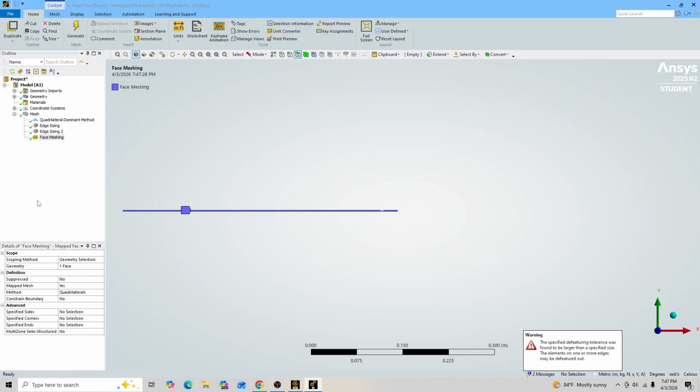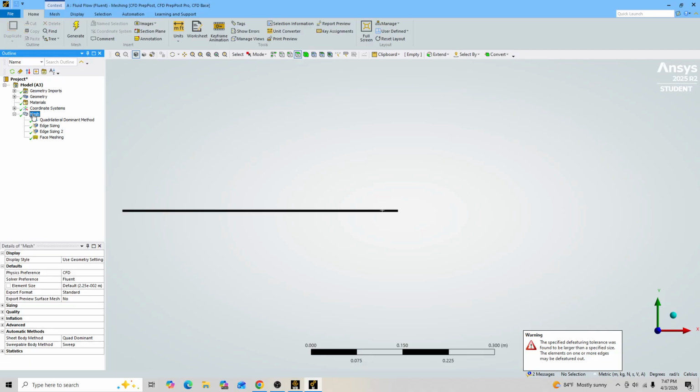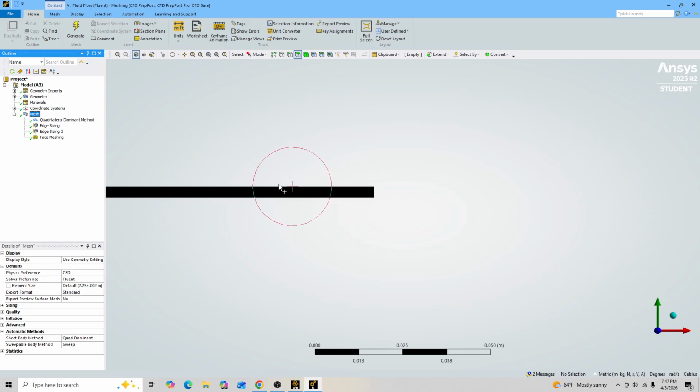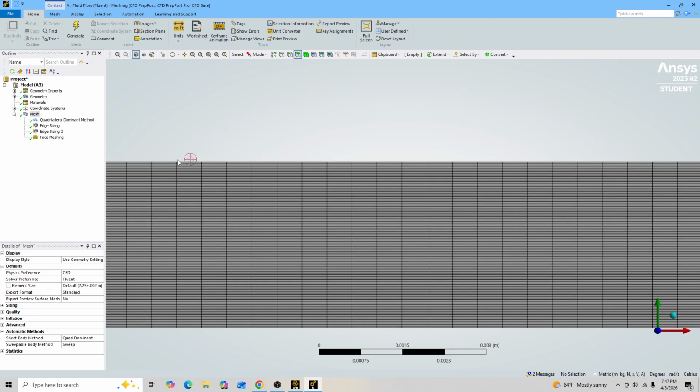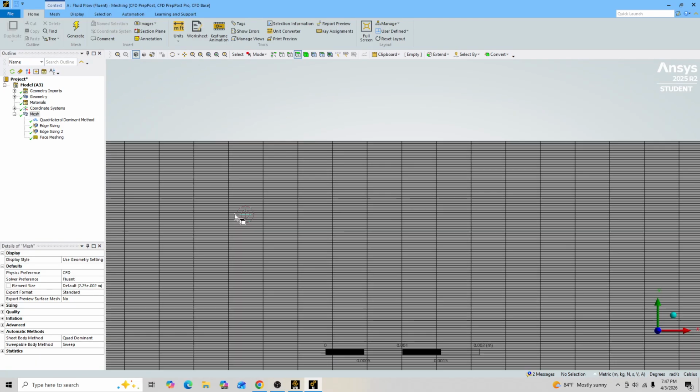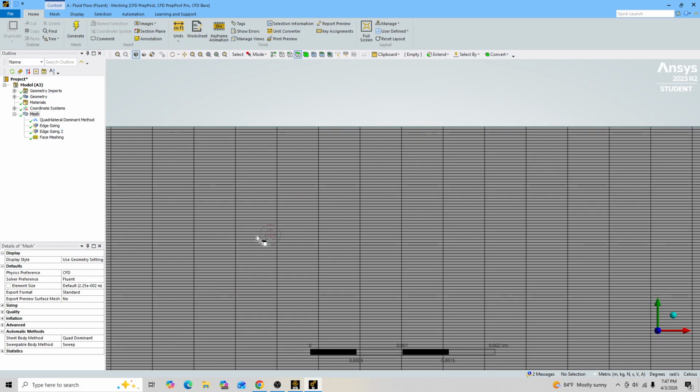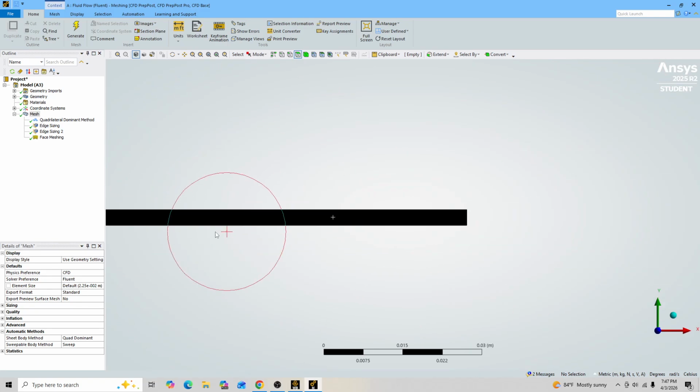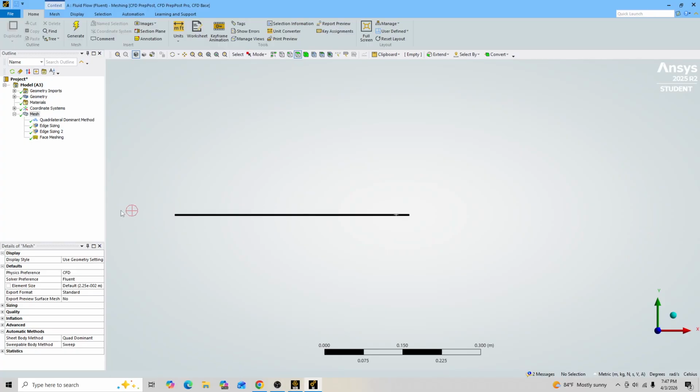Okay, and it should have. Alright, so yeah, you can go ahead and check. By clicking on mesh, you should get a long flat plate that's completely black. But when you zoom in, yep, like that, you can see our divisions here and our mesh. So that's exactly what we want it to look like.